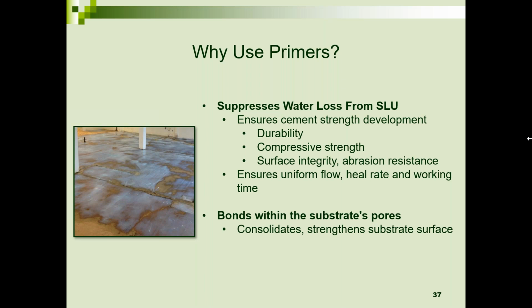Primer applied to the surface gets absorbed into the substrate and strengthens it in some way. This is not to say that you could ignore shot blasting or grinding. If you have a weakened surface or contamination, putting a primer over it does not solve the problem. You still have to do surface prep, mechanical potentially. The binder or primer just helps with the integrity of the surface, adds a little bit of muscle to it.